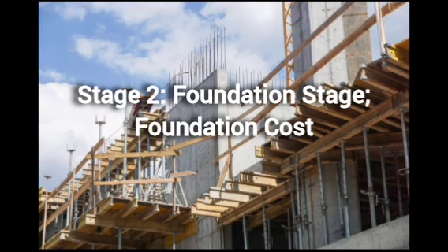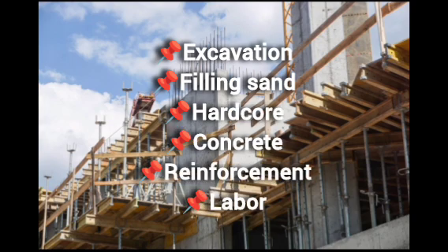Stage 2, we have the foundation stage, which includes the foundation costs. We have excavation, we have the sand filling, we have the hardcore, we have the concrete, we have the reinforcement, we have the labor. Foundation cost depends on the soil condition and also the building size. Weak soil can require additional reinforcements, which also increases expenses.